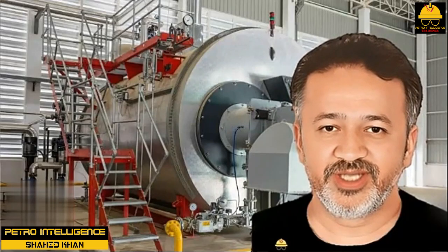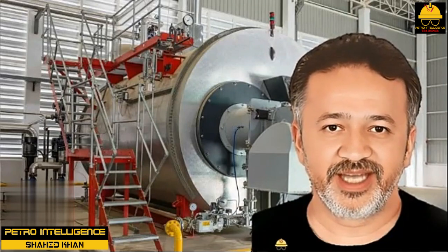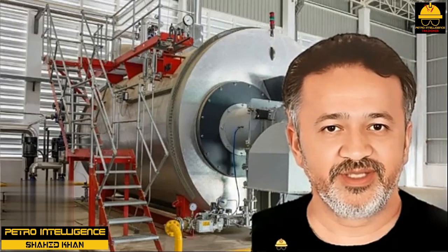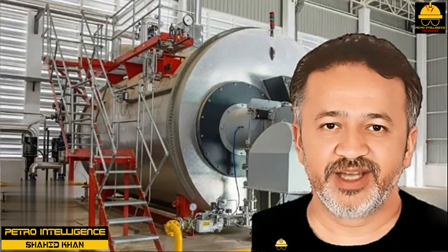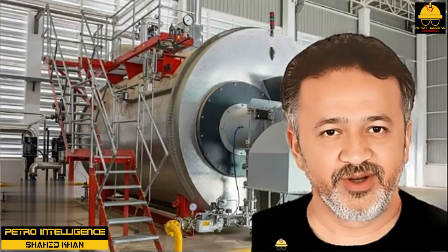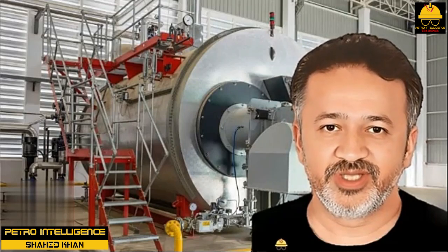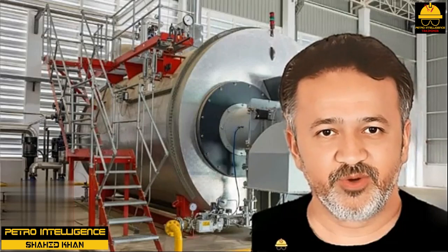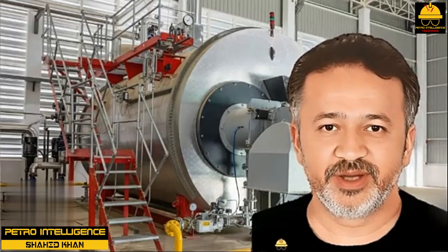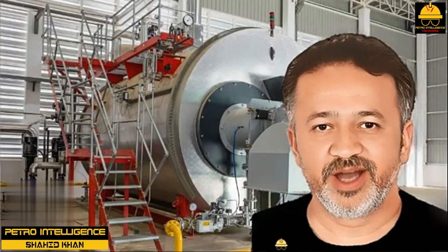Steam turbine surface condensers. Steam used to drive a turbine can be extracted at an intermediate pressure for further use of the low-pressure steam. Rarely is the steam vented to the atmosphere, as this wastes steam, and the condensate is also lost. Many turbines exhaust steam under vacuum to a surface condenser. The lower the pressure in the surface condenser, the greater the amount of work that can be extracted from each pound of steam. Discounting the presence of air leaks, the temperature inside the surface condenser determines the pressure of the steam exhausting from the turbine.